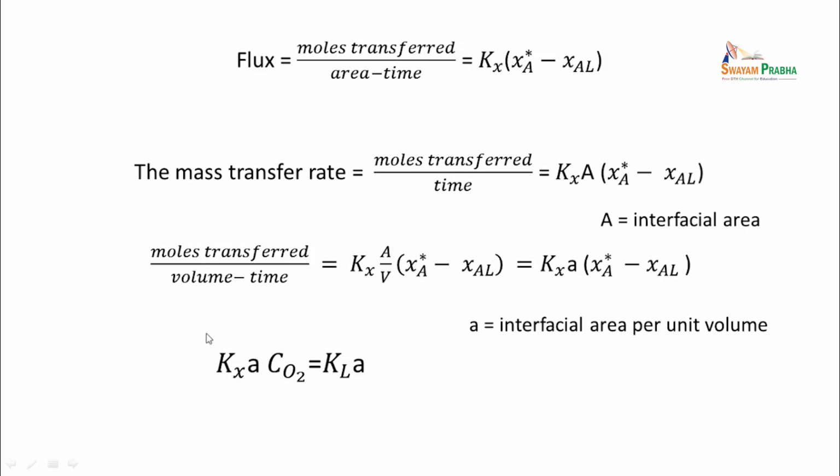So the overall mass transfer coefficient, this is on a mole fraction basis. If we multiply by the total oxygen concentration in the medium, it becomes on a molar concentration basis. The mass transfer coefficient of oxygen on a molar concentration basis, and also on a volumetric basis, is KLa.